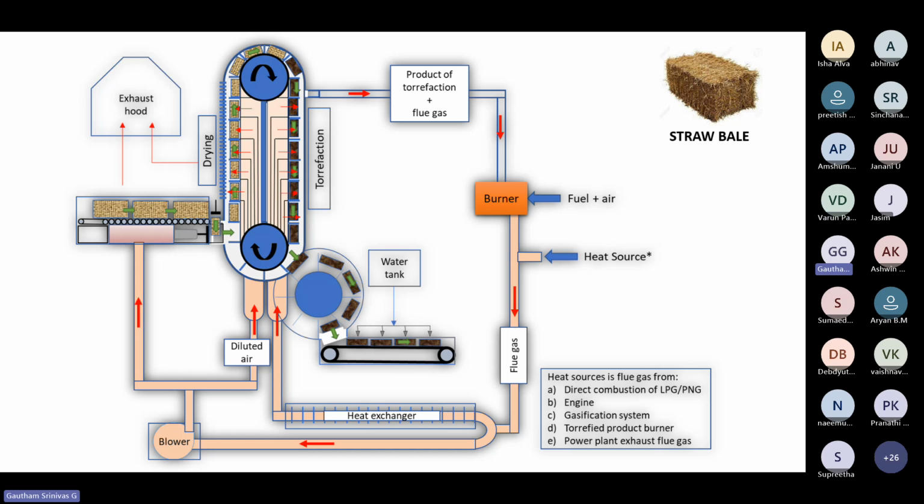The ambient air at 25 or whatever temperature, they're mixing it with this flue gas, which is at high temperature. So you have a lower temperature. Okay. So the temperature remains below whatever, 200, 100, 150, right, for the drying. And similarly here. Okay, so you have two streams for drying. My question to you is, why do we use direct mixing of air in this case and not in this case, where we are using a water operated or air operated heat exchanger?